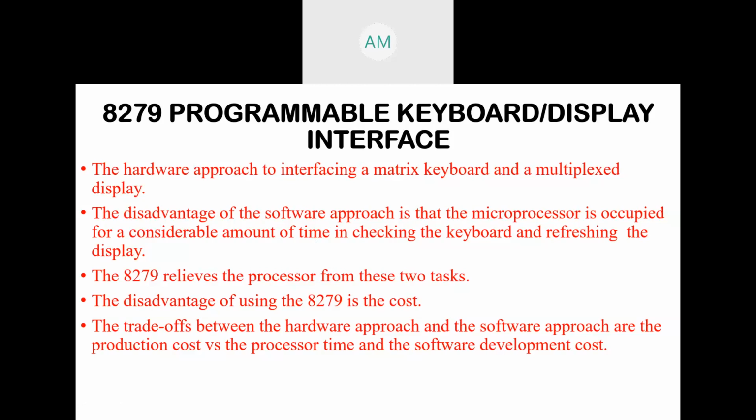There we could find the disadvantage: the amount of time that was required to check whether the keyboard is pressed or not, and also to refresh the display, where we have to read the new key and refresh the display. So the amount of time consumed there was more. That was the disadvantage of using the software approach, that is the instruction set.